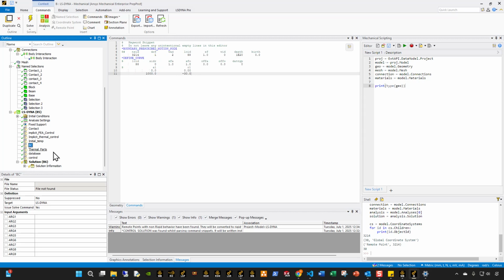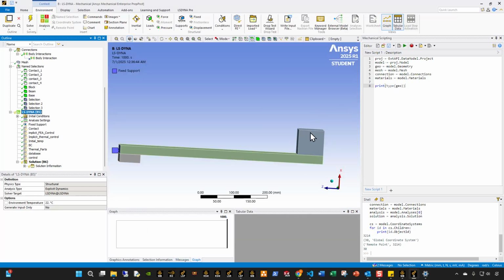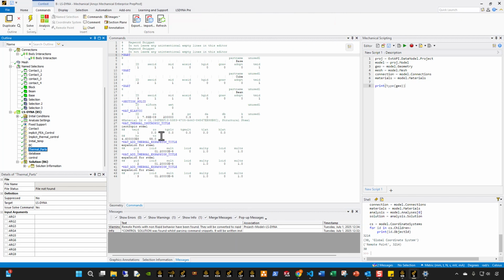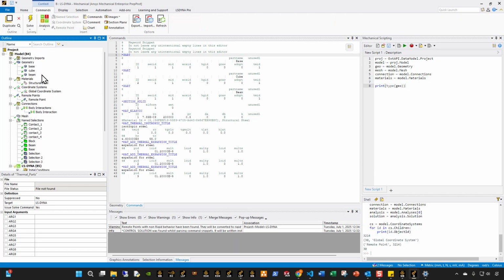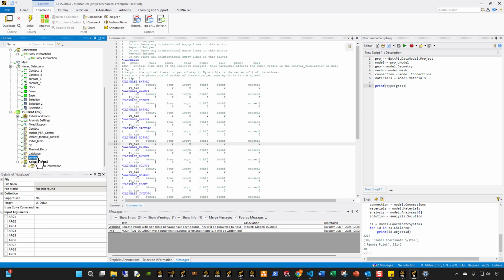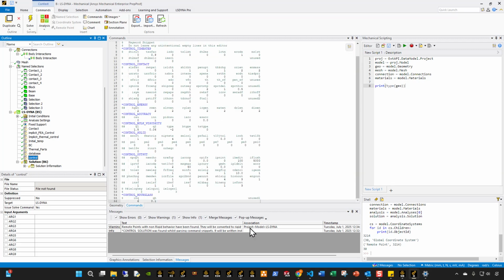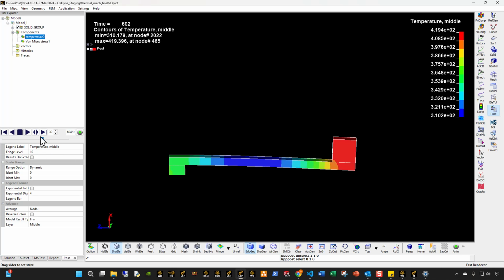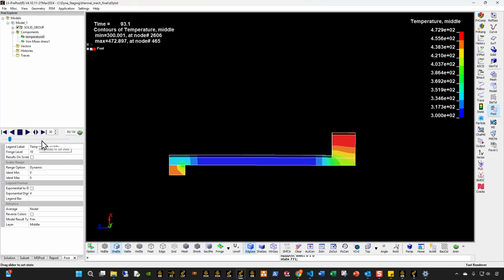You have your initial temperature, you have your motion, the actual displacement of the plungers applying the deflections. You have your thermal part, which replaces the part that's written out by default by the solver, and you have your database card and your control cards, and together they serve everything. And then this is the solution that you're looking at, right? So you have a very clean overall solution here. That's going to be a thermomechanical problem. And right here is how you do a thermomechanical co-simulation inside LS-DYNA.